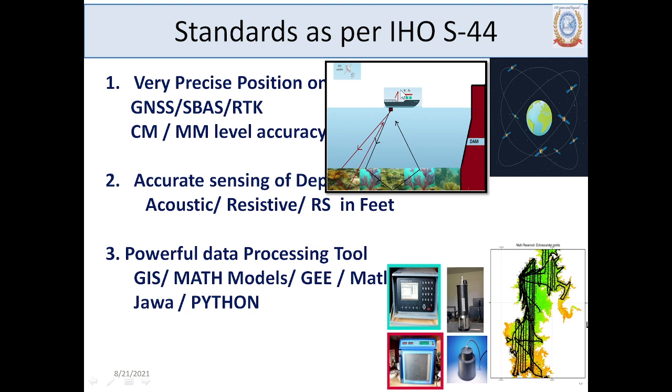Because I said the position accuracy I am already giving you with the satellites in centimeters, and depth also I am giving you in centimeters. In such cases, you could produce a very good quality area capacity curve, or the storage capacity, or the sediment rate, etc. These are the sensors which are used in the boat.